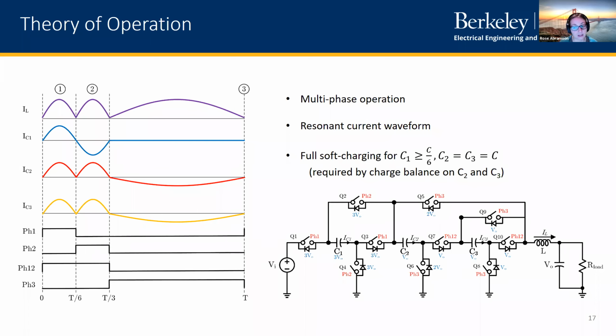So you may still be able to get a very small form factor of total capacitance because you don't need to use very high voltage rated parts for C2 and C3, whereas C1 now does need to be rated for a bit higher voltage, but it has a much lower capacitance requirement. So this kind of balance between the two helps us maintain good smaller converter size. So we don't have to use huge banks of very bulky capacitors for this topology.